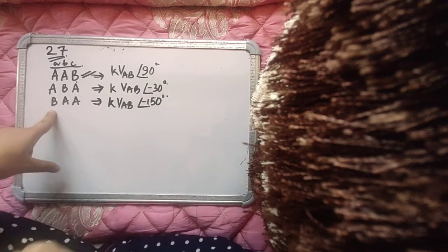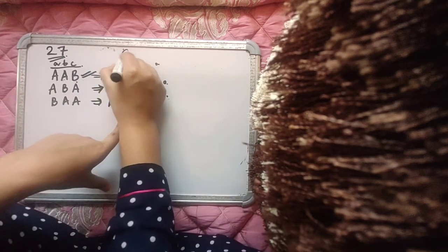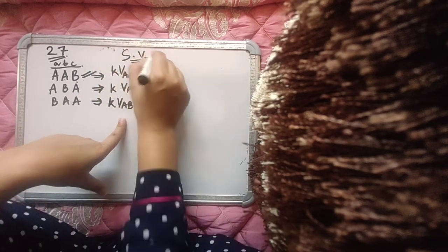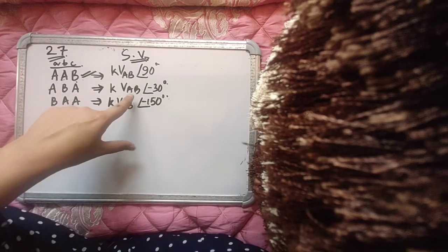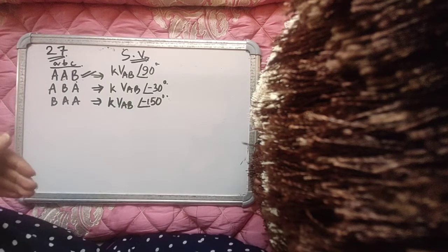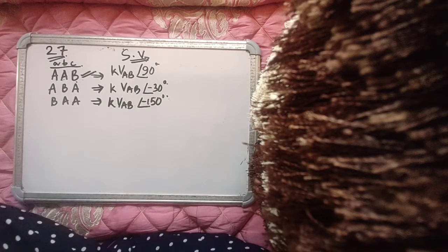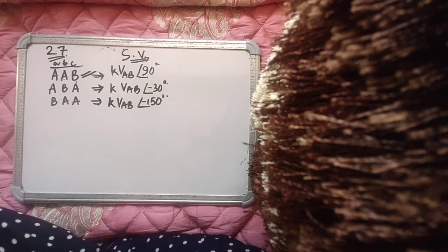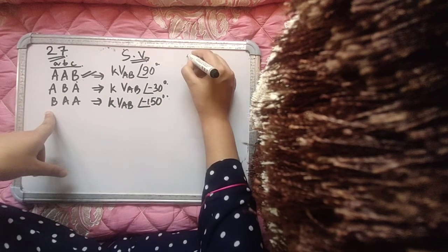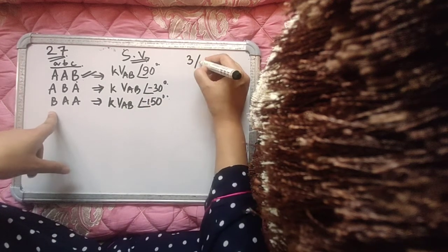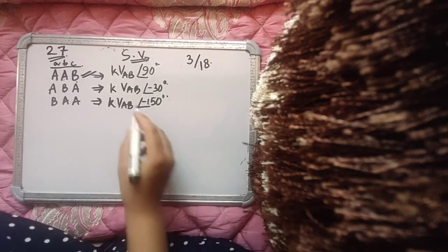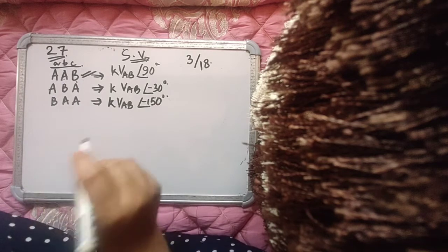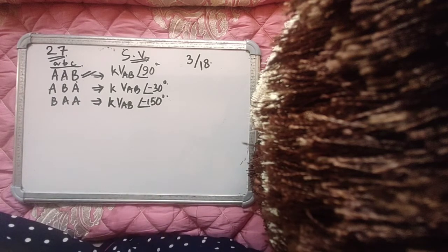Now, the output voltage space vector, the output line to line space vector, is a function of the input line voltage VAB, and if you use the other states, it will be a function of VBC also, a function of VCA also, and so on and so forth. Because please remember, right now we have found the space vector of only 3 out of 18 switching states, right? So if I want to draw the output space vector diagram.